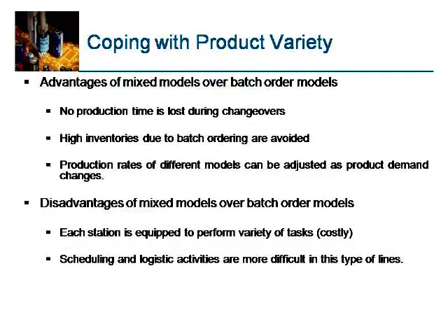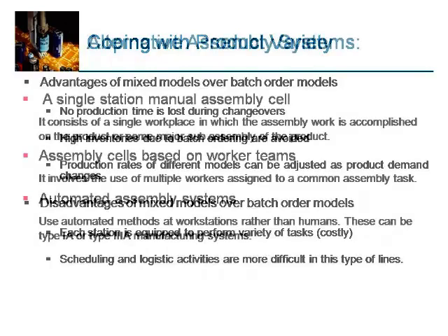Advantages of mixed models over the batch order models: no production time is lost during the changeovers, high inventory due to batch ordering is avoided, and production rates of different models can be adjusted as product demand changes. Disadvantages of mixed models over batch order models are that each station is equipped to perform a variety of tasks, and scheduling and logistic activities are more difficult in this type of line.